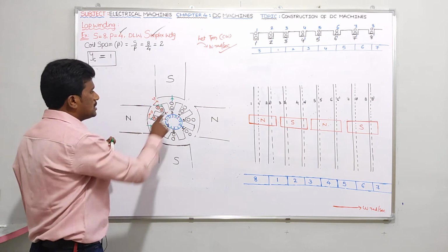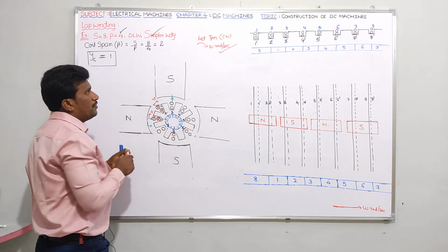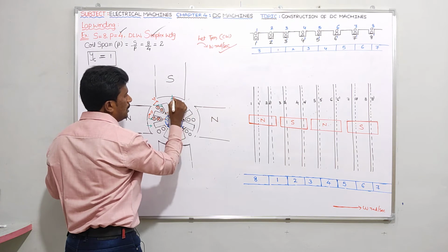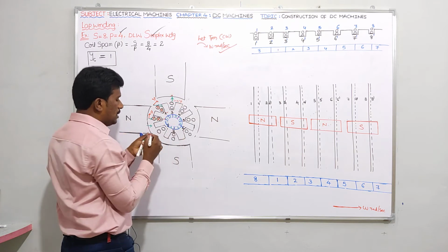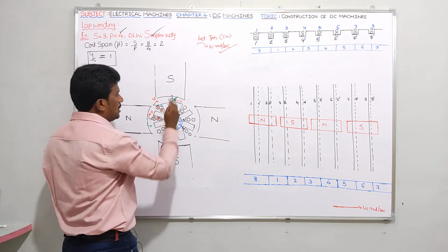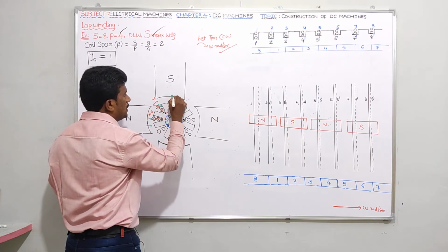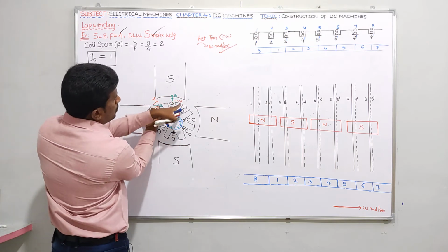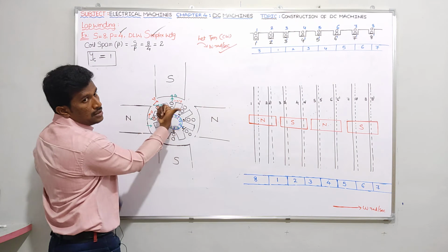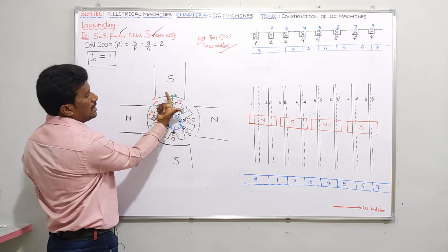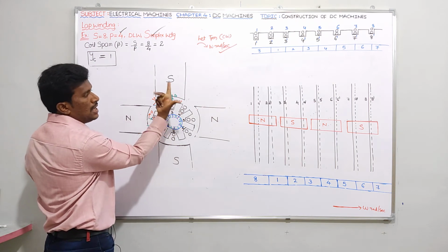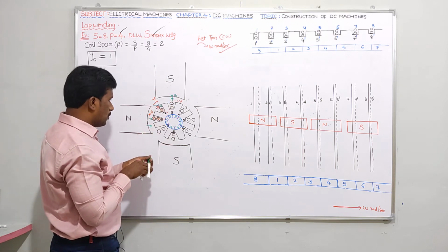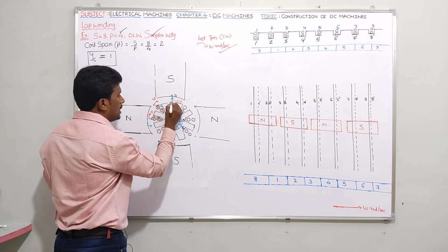Now tell me, at the third slot, what is the tangential motion, guys? For clockwise rotation it should be like this, no? And this is the direction of linear velocity of the conductor, and this becomes the direction of flux density. Now apply Fleming's right hand rule. The thumb indicates this red color, the velocity of the conductor. The forefinger indicates the direction of this green color, and EMF is induced in that conductor. Means what here? Dot. So in slot number 3 the direction of EMF is dot.